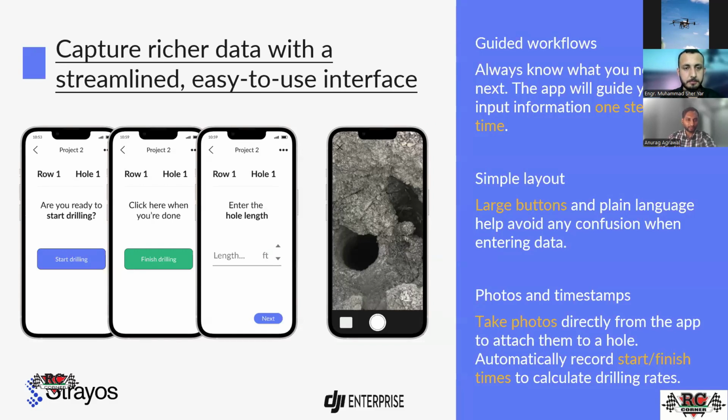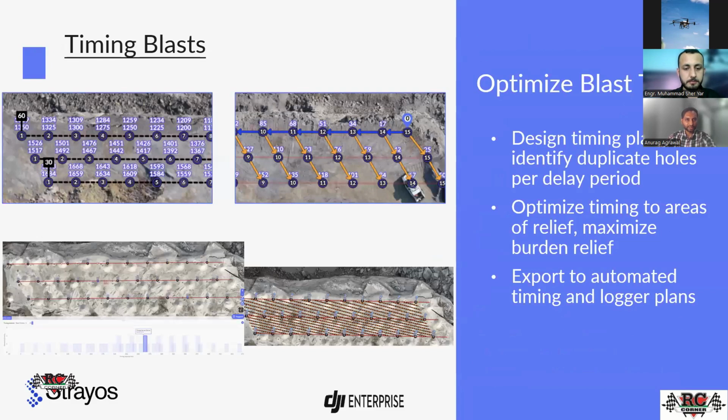So after completion of drilling design and loading design, next planning is the timing design. And we always face issues while planning the timing, because we are not considering timing design based on the burden length. We are always planning to keep an 8 millisecond gap at least between the holes and rows.